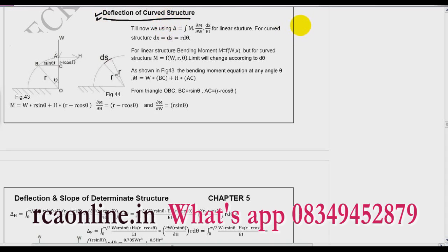So till now what we have done, friends, is that if I have a beam which is not curved but linear with some load, and if I want to find the deflection, then I was using this formula. So what is my deflection? Deflection is integration of the bending moment over the total structure, M, and then partial differentiation of that bending moment with respect to the load applied at that point. So in this case it will be P dx over EI.